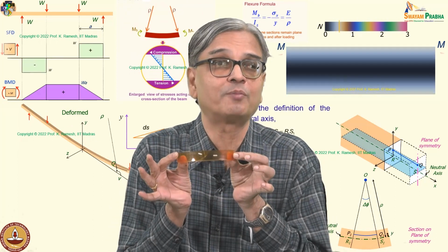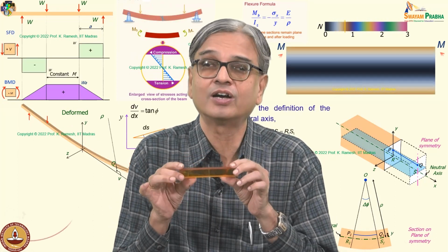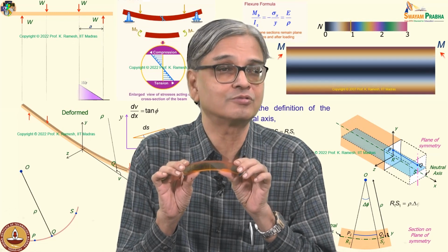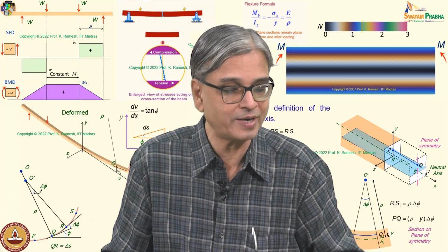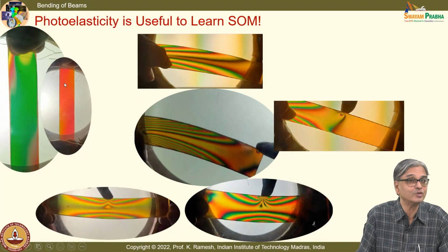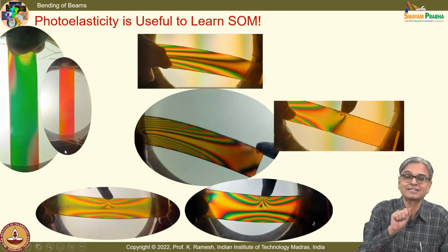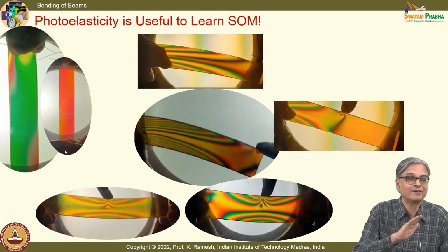I have just given you a model like this, and in your exposure to photoelasticity lab, people have provided this beautiful fringe pattern. These are all recorded by you in the laboratory class. I picked some of them. So, you have a grip. I have tension applied, and compare these two. This is done better. You find there is uniform color. So, now you agree, when I apply an axial force, I get only uniform color.